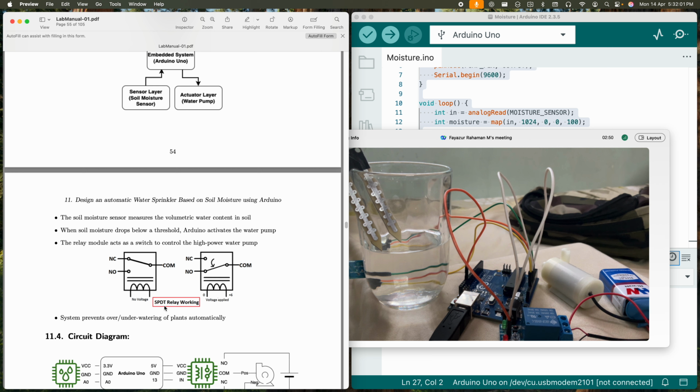In fact, it is a single pole double throw switch. It's a switch basically. You can see this is the pole, and you have the common terminal. It's normally connected to one of the terminals in the default state. That means when the coil has no voltage, in the rest position, this pole will be connected to normally closed. That's the reason it is called NC, normally closed. This is how the circuit is completed.